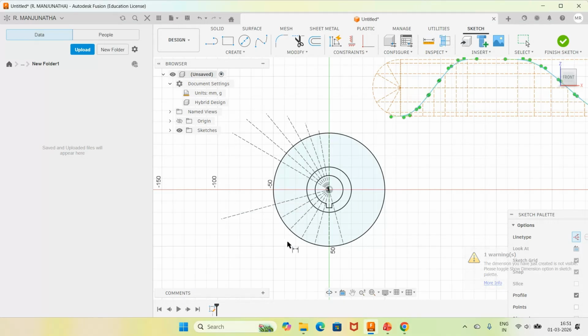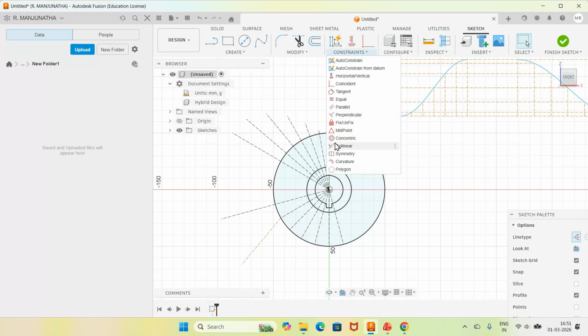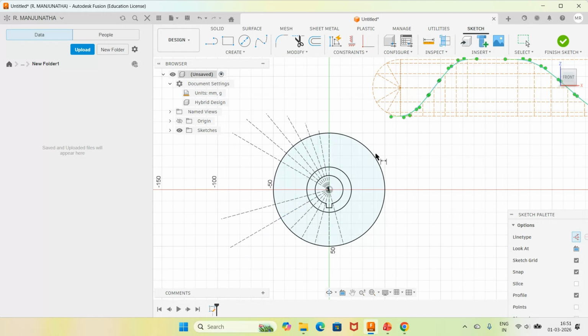Okay. Now we have the extreme point. Then it starts receding now. It has to come down now. Again, I will go for collinear, select between this line and go to dimension between this and click on three dots here, measure, select this line and say enter.